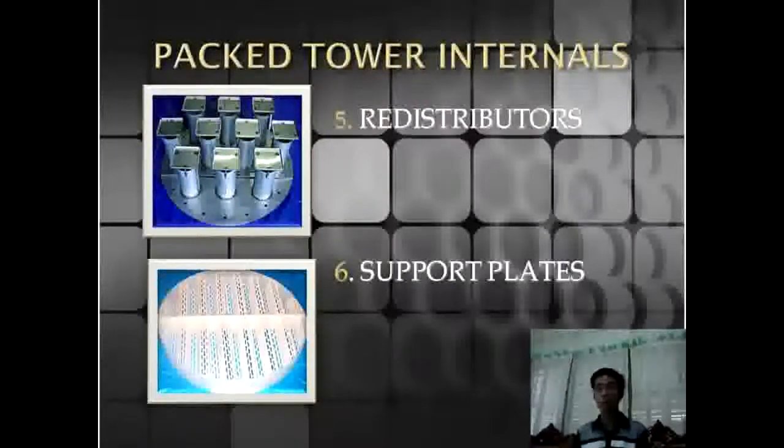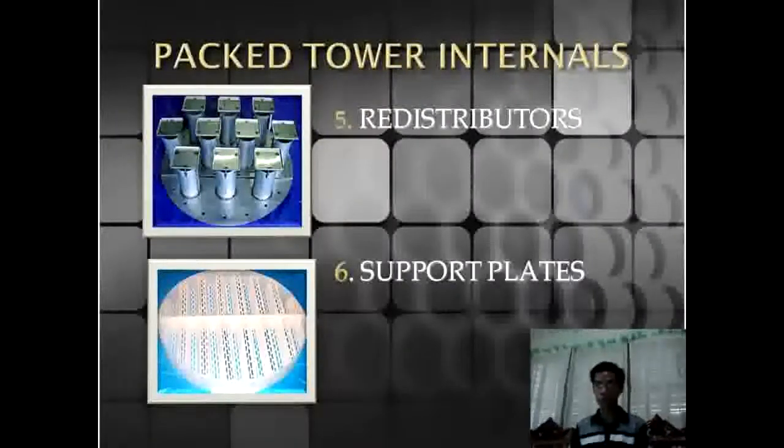There are also support plates inside the packed tower, which are usually made of screens with a large open area so that flooding does not occur. And then lastly, we also have redistributors, which are used to introduce and/or to mix liquid at regular height intervals.